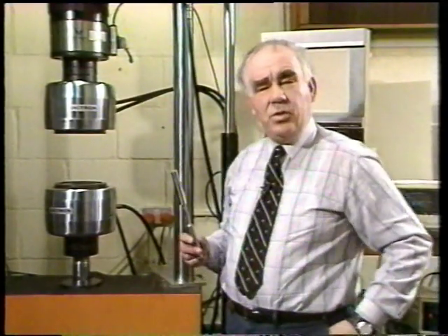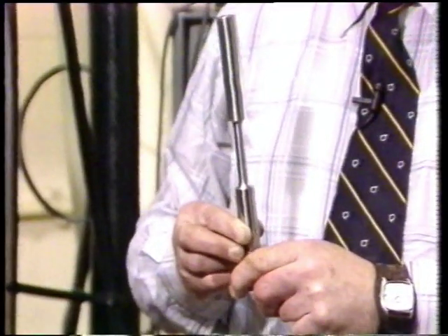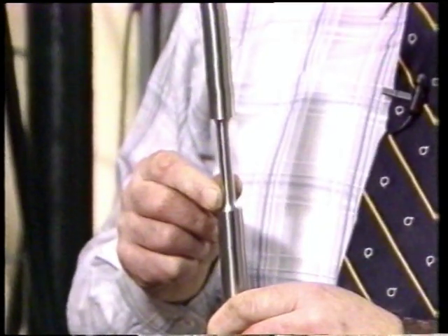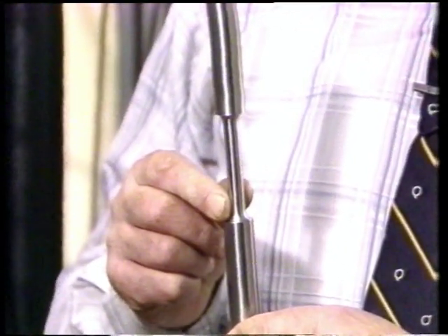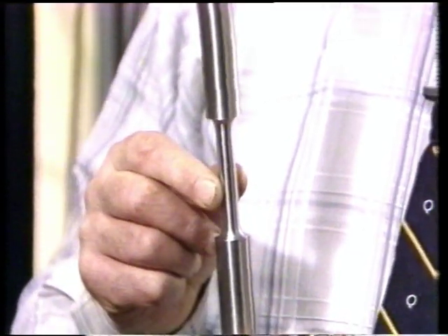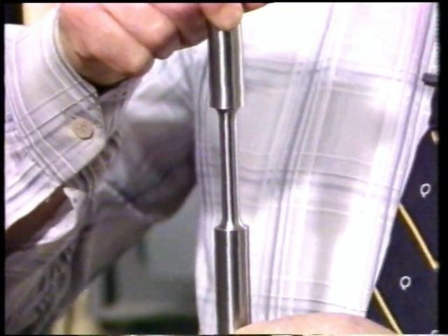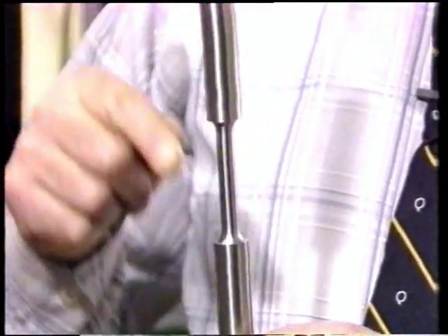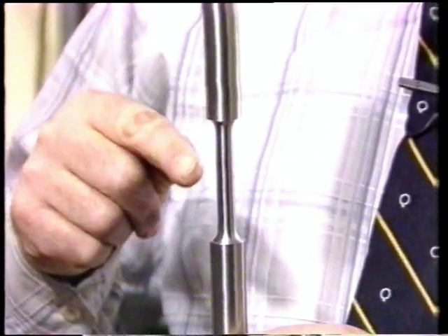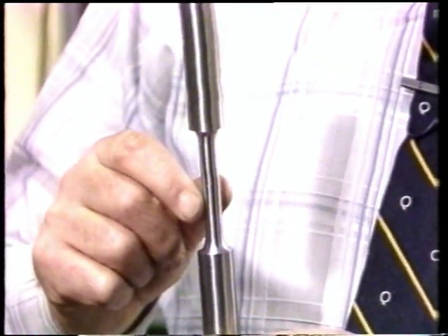Here's a typical tensile test specimen. This one's made of mild steel. The important feature is this uniform section in the middle, the gauge length, which has a constant cross-sectional area so that we can convert the forces applied into stresses on the material. The two thickest sections are for holding in the grips, so we can transmit the force. And the radius regions here at the shoulders are to avoid unnecessary stress concentrations, because we want the specimen to fracture somewhere along the gauge length.